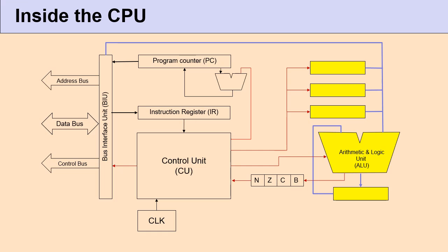Since the ALU output is only connected to register A, the output operand of any instruction that involves the ALU has to be register A. In other words, whenever the ALU carries out some operation, its output will always be stored in register A. Also, whenever the ALU carries out an operation which requires two inputs, one of the two inputs must come from register A. So in this case, the register acts as both input to the ALU as well as output of the ALU.